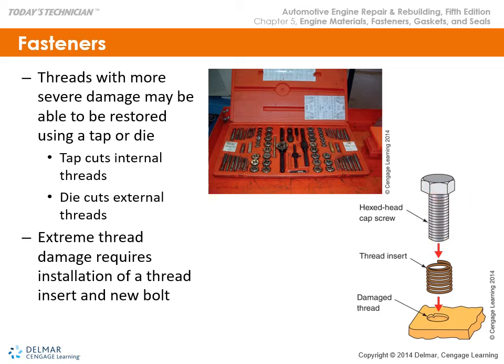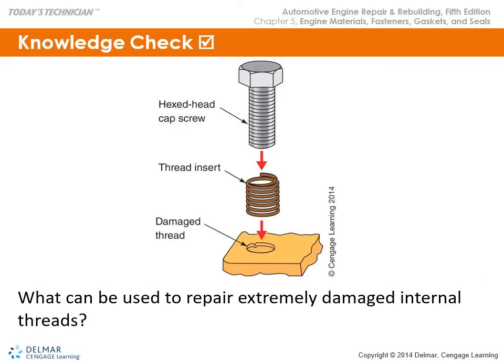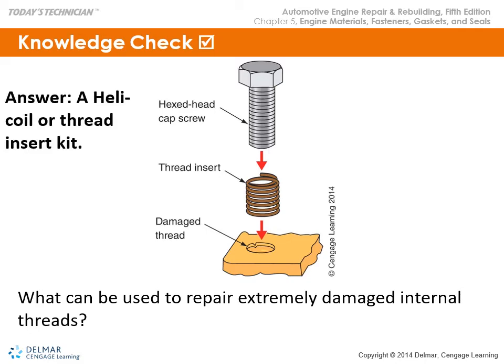It takes some finesse to utilize the helicoil and how to dress the hole and get the part to start correctly without deforming the coil, and then knocking out the tang that's left on the bottom when you're done. They're not showing the tang here, but it is a process that we're going to do in shop and demonstrate.